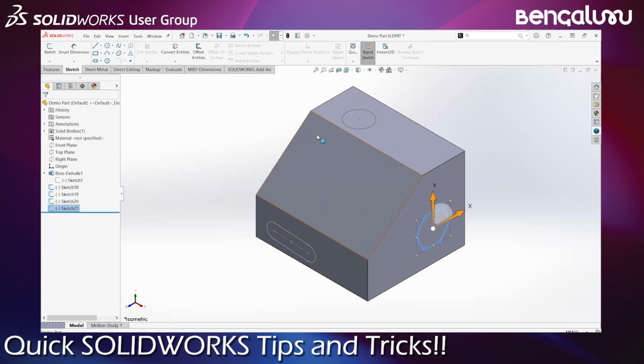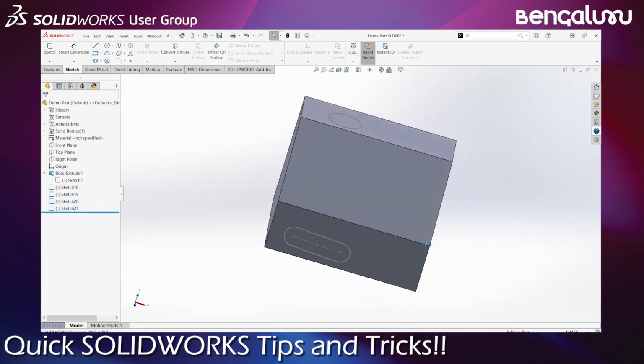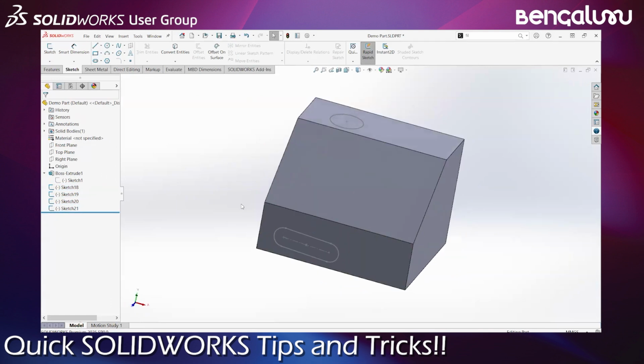But this saves you the time of having to click on a face, then say sketch, and then take the sketch command. So if rapid sketch is on, you can simply go on creating sketches on different faces. SolidWorks will ensure that each sketch falls on the right plane or face that you selected. So all these are few things that will improve your productivity, right?